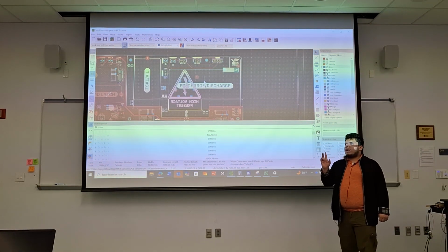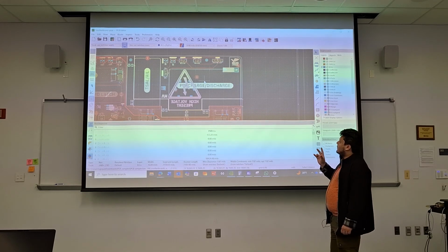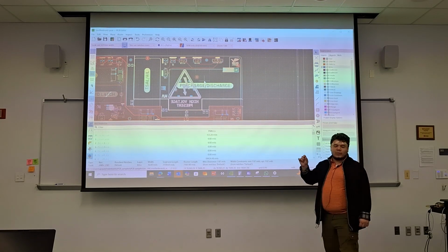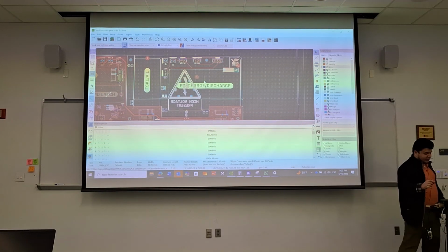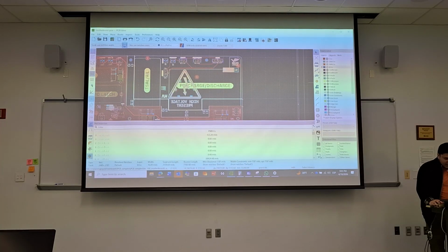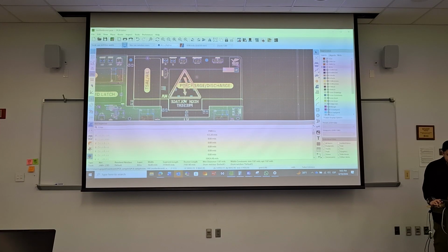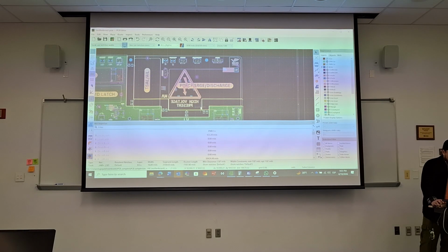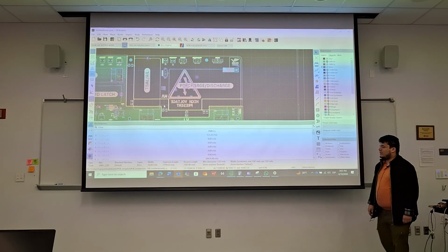But you gotta realize, I mean, sure, there's quite a bit of voltage, a significant amount of voltage, right? It's a high voltage card. You can get away with ground, pretty sure, on the second layer. Now, yes, since it is such high voltage, you do want to avoid having a ground too close.